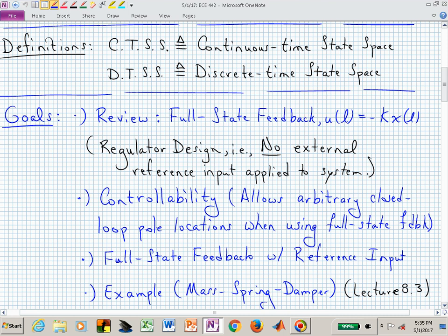Maybe you place 2 poles of a 10-pole system at this dominant location informed by the circles, the hearts, and the wedge, and then maybe you put all the others at the origin. If you had 10 poles, you would do 2. Those would dominate. Those would be complex conjugate at those circle, hearts, and wedge locations, and then the other 8 would be at the origin.